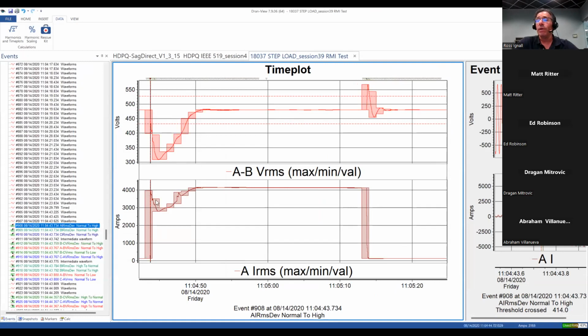You can see what triggered, and I'm already zoomed into what the effect on the voltage was and the current. So you can see our current goes from basically 0 or just a couple amps all the way up to 4,000, or actually peaked over here at, what was it, 7,000? About 7,000 amps, and look at how the voltage dipped at that particular period of time. So basically when this turned on, this would have created a sag or a dip event, and some loads may have been affected by that.